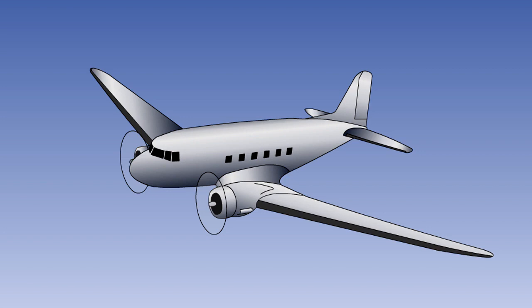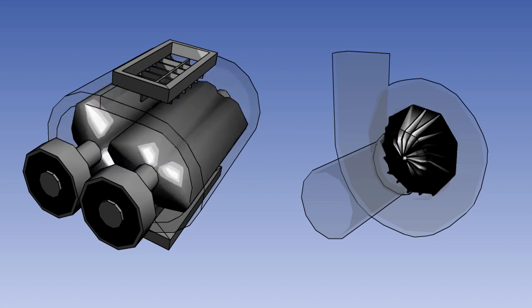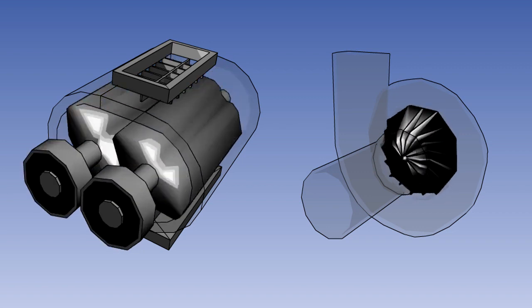A cabin air supply may be provided by blowers driven through the engine accessory gearbox, or by turbo compressors driven by bleed air. Such systems are necessary for piston-engined aircraft and are used for some turbojet aircraft, where the air supply from the compressor is considered to be too dirty or contaminated for use in the air conditioning system. These blowers operate in a similar manner to the superchargers fitted to some piston engines. They may either have a centrifugal or a positive displacement type blower fitted.